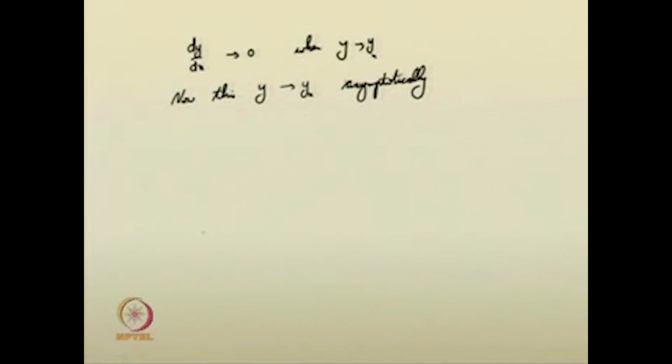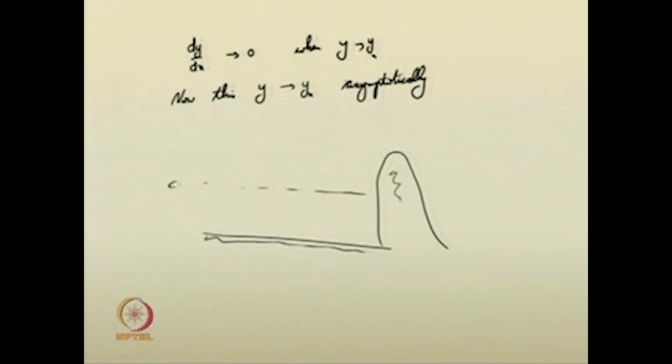Say in this particular case, you have such an obstruction there, critical depth line, normal depth line, and you want to compute the M1 profile. This M1 gradually varied flow profile reaches the normal depth asymptotically. So, theoretically, according to the mathematical case, it will reach only at an infinite distance. That is not feasible for us. We cannot spend that much time.